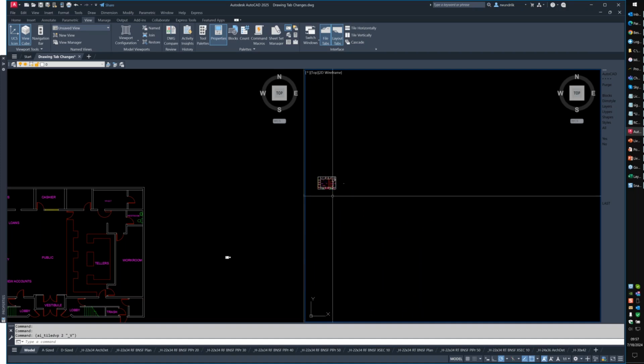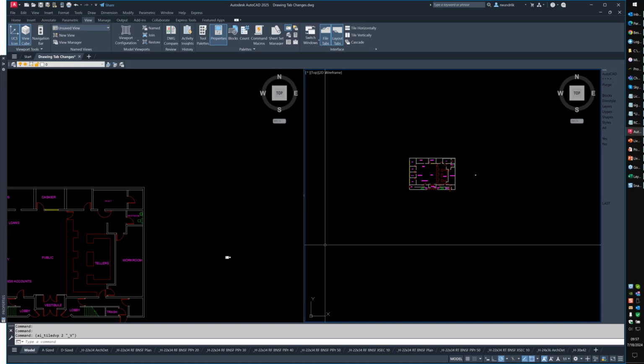It also, splines especially, are problematic the closer you get to 0, 0, or the smaller you make the spline. So if you have a spline object and you scale it very small, it will no longer be a spline object. It'll become chunky because of how the calculations are done for the spline nodes. And like I usually tell people, don't use splines. Those are terrible things. AutoCAD gave them to us. Just because we have them doesn't mean we should use them, because they are limited in functionality for what we can actually do with them. Personal preference, right? I'll get off that soapbox now.